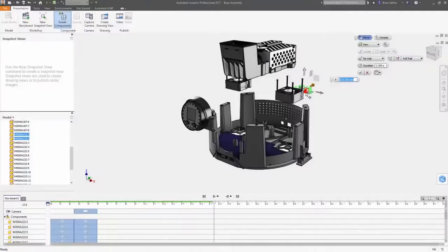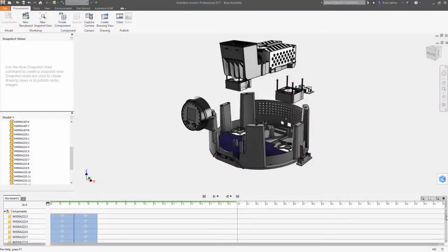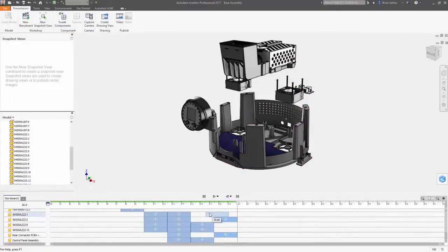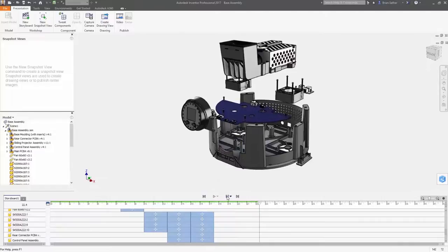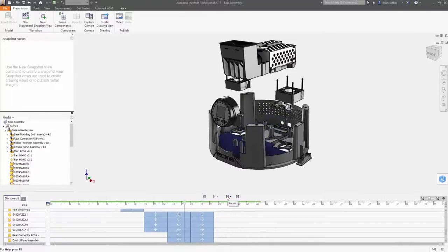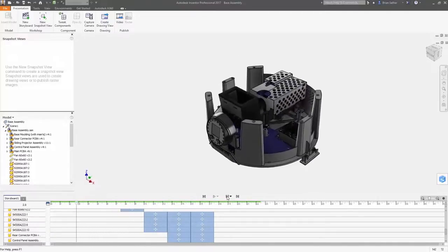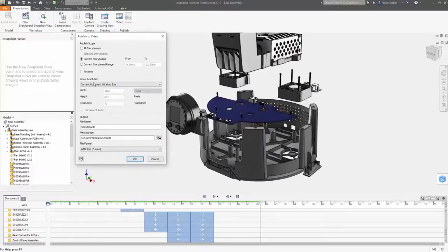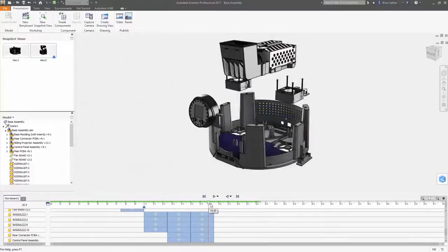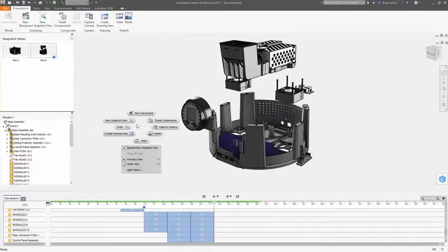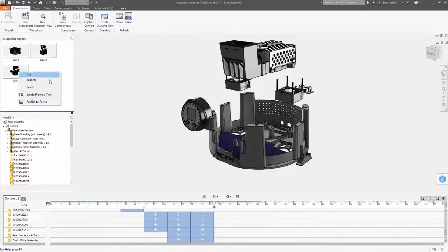As you move components around, each action is captured on a new timeline inside the storyboard panel. This visual representation in the storyboard clearly displays each sequence of movements and provides you control over the camera position and details of how each action will be displayed on the screen. You can create multiple storyboards to organize complex animations into shorter, more manageable segments, and each storyboard can be exported as an individual video clip or as part of a complete collection.